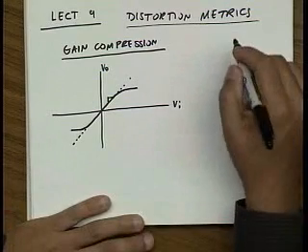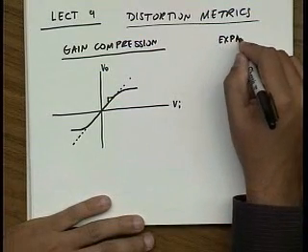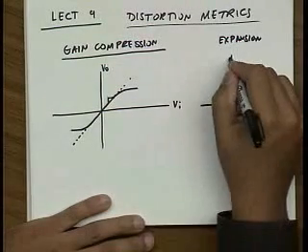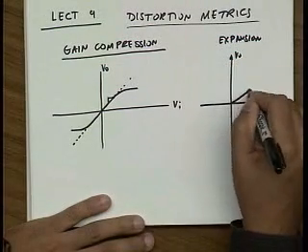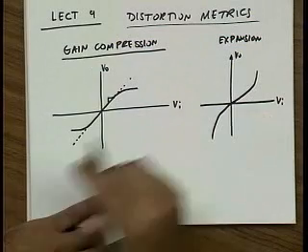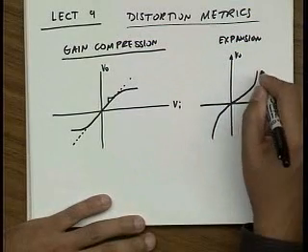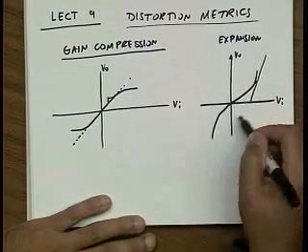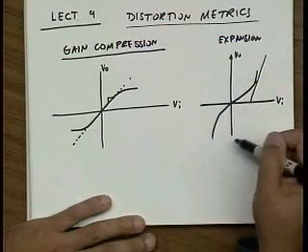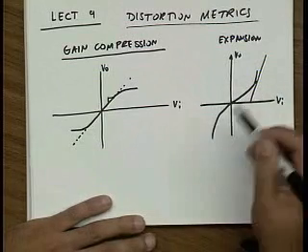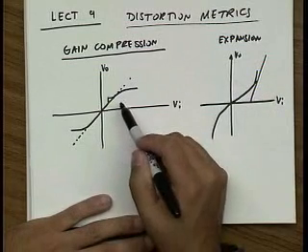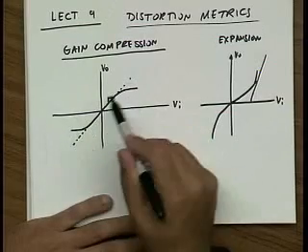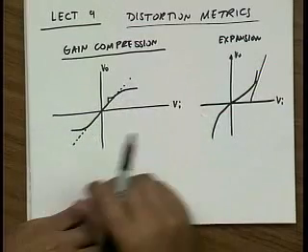Now you can also have expansion, less common, but gain expansion means that actually this thing might look like that. So the slope increases at high level inputs. Now even though you might observe this for small inputs, eventually if the input gets large enough you will experience compression. Because most systems eventually will compress, let's say at VDD, the power supply voltage.